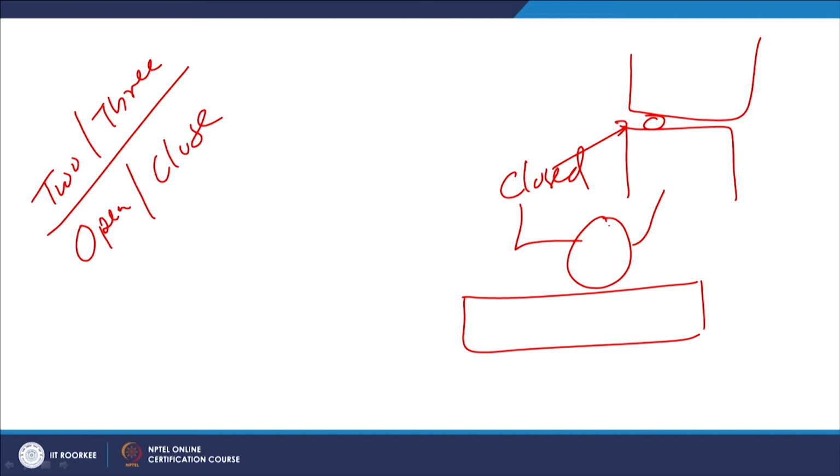So, that forms the closed abrasion, and when the abrasive particles are allowed to move freely over the metallic surface, it leads to open abrasion. And then, according to the kind of loading, there can be low stress abrasive wear conditions or high stress abrasive wear conditions.